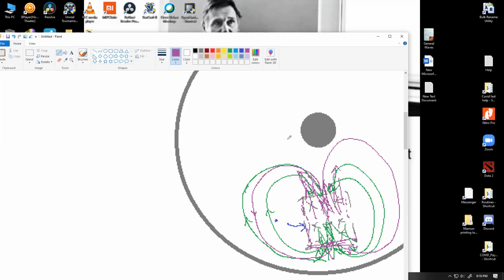How many electrons are going to move, or how fast they are going to move, is very much dependent on how fast the disk was rotating. So if the disk is rotating at a very high speed, you can extract energy pretty fast. So it can work as a very efficient braking system for high-speed vehicles. But for low-speed vehicles, it's not going to work that well, because if the disk is rotating at a low speed, you're not going to have that much cutting, you're not going to have that much current. So the rate of conversion from kinetic to heat energy wouldn't be as effective.